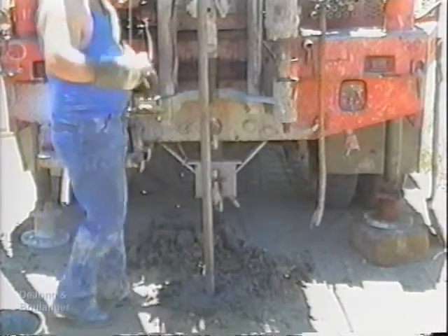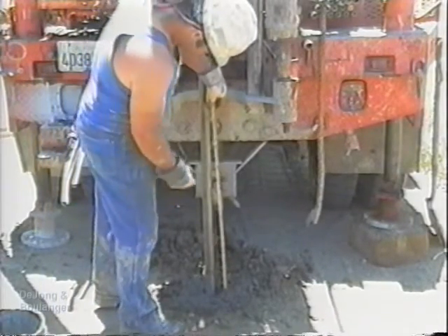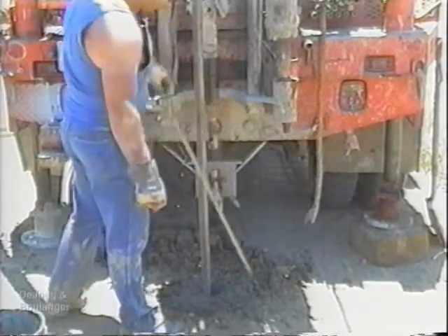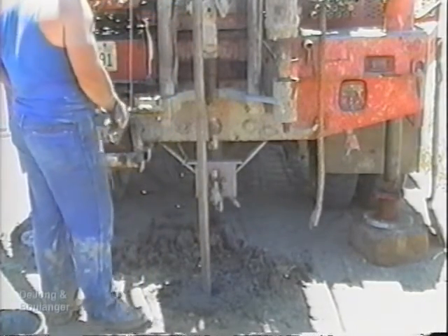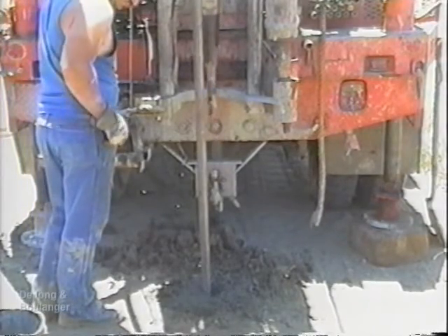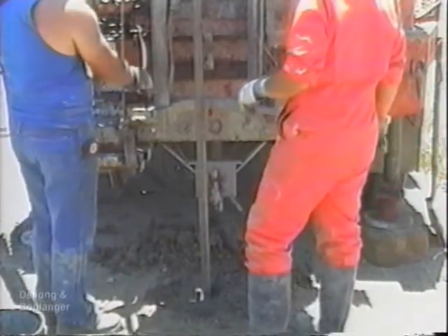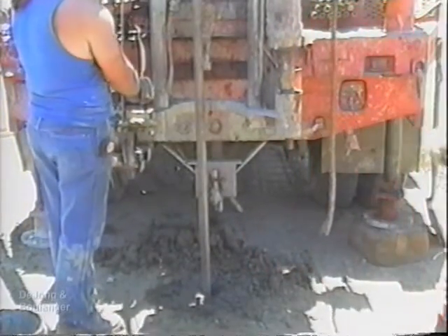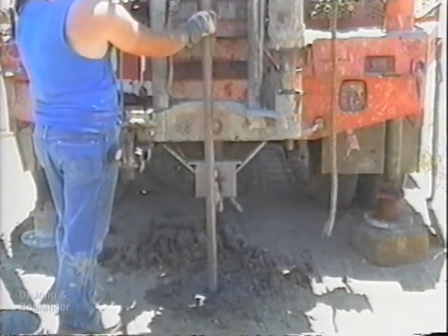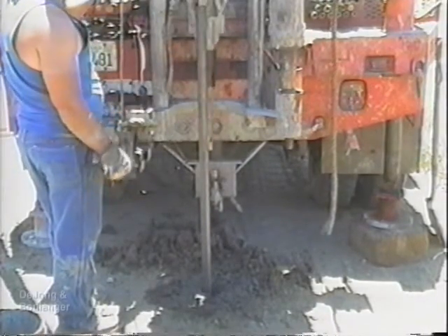To take a sample, a tube is attached to the bottom of the drill rods and lowered into the borehole. The sampler is then pushed downward from the bottom of the hole a distance about 5 inches less than the length of the tube. To minimize the sample disturbance, the sampler is pushed into the ground at a high constant speed. The sampler should not be driven by a hammer, as this increases sample disturbance. After the sampler has been pushed down, the drill rods are rotated to shear the end of the sample, and the sampler is removed.